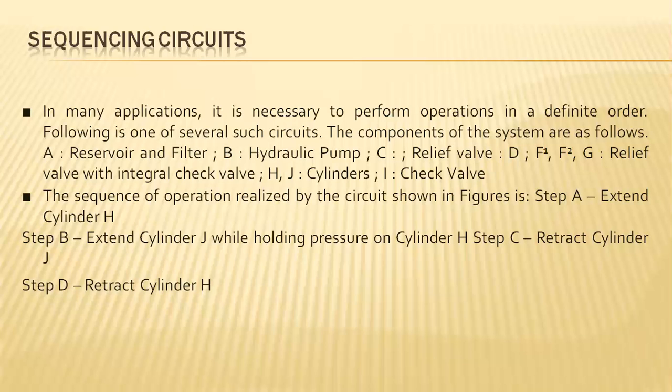So the components of the particular system which are designed as per the hydraulic strategy commonly have the oil reservoir and filter, and the hydraulic pump, which acts as a prime mover and pumps the fluid in pressurized conditions to the system, and pressure relief valves which act to leak the small amount of pressure which keeps the entire system in unsafe operating conditions.